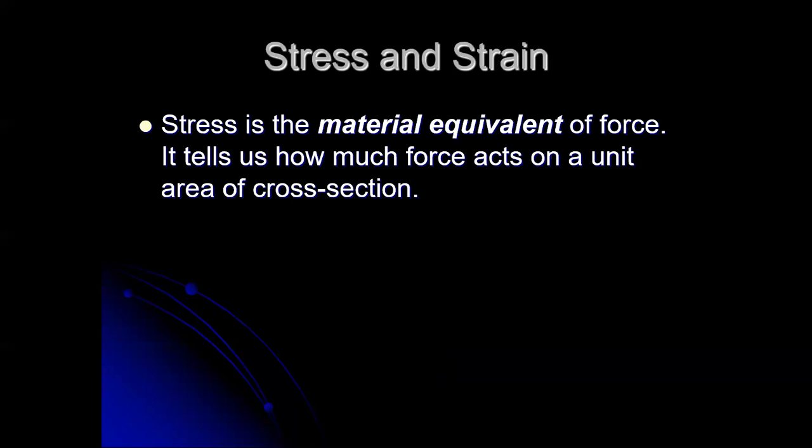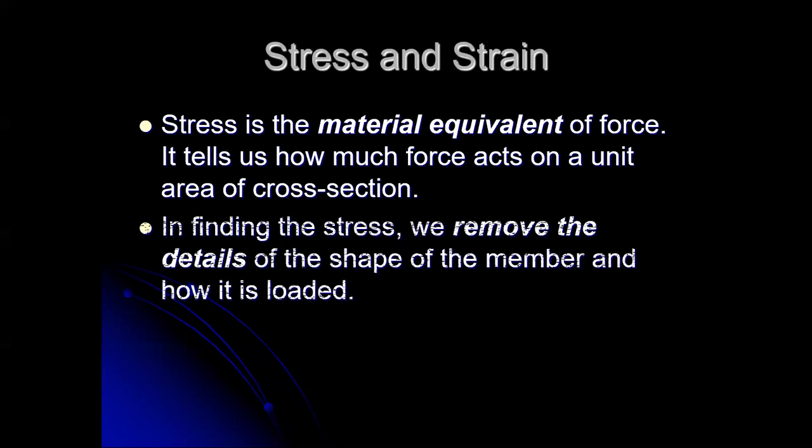So stress is what we call a material equivalent of force. It tells us how much force acts on each square inch. And it simplifies things quite a bit because it actually removes the details of the shape and how it's loaded.